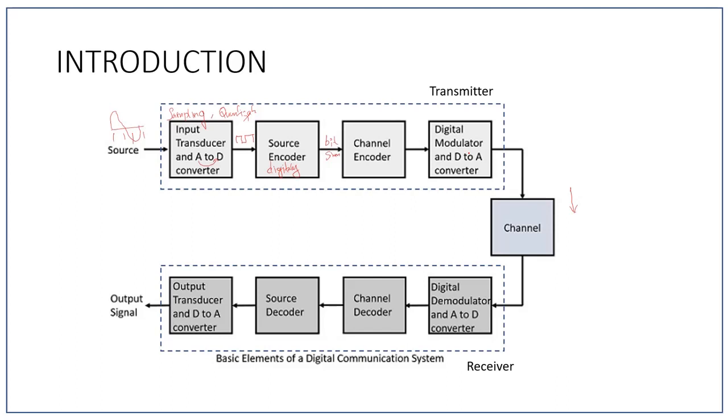In the digital modulator, we have different modulation techniques such as amplitude shift keying, frequency shift keying, phase shift keying, etc. All these digital modulation techniques are used so that the message will have enough energy to be transmitted. The message after channel encoding doesn't have enough energy to be transmitted over a higher distance. So the main purpose of the modulator is to provide energy to the signal so that it can be transmitted over higher distances. This modulator block takes the symbol occurring at every Ts seconds, and it is mapped into a continuous waveform, which is sent across the channel.